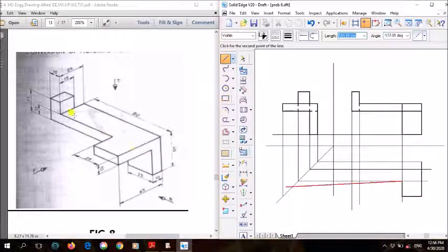And next, to the left side, 80 minus 25, how much will you get? This whole is 80 from here to here, and this is 25, so you'll get this part, 55. So to the left side draw 55, and from here upwards it is 25, and then finally join it here, right? So we have drawn this surface. In the top view this surface is visible. Just next to this surface is visible, how much is it? 15 by 10 mm, right? So you need to draw it here.